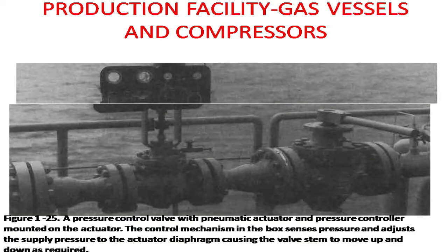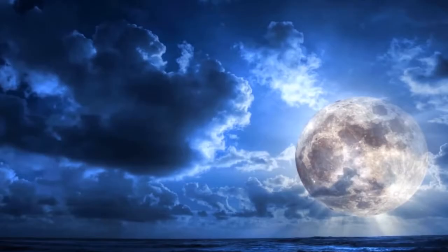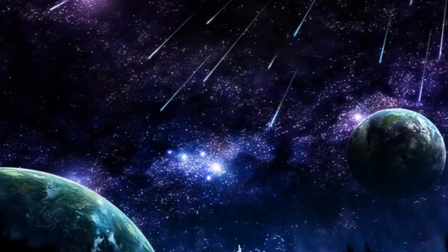Now, the positive choke takes over and keeps the production rate within limits should the adjustable choke fail. On offshore facilities, another high-risk situation, an automatic shutdown valve should be installed on the wellhead, and it is required by federal law in the United States and in Nigeria also. In all cases, block valves are needed so that maintenance can be performed on the choke if there's a long flow line.